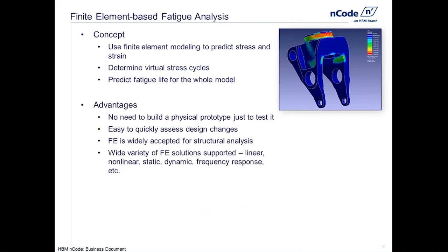The advantage here is that we don't have to have a prototype. It's easy to address design changes quickly. We've been doing FE for quite a while, so it's an accepted method for doing structural analysis. And we have a wide variety of solutions from FE. We can do nonlinear or linear. We can do statics. We can do dynamics. We can look at frequency response. So there's a wide-ranging list of capabilities available.